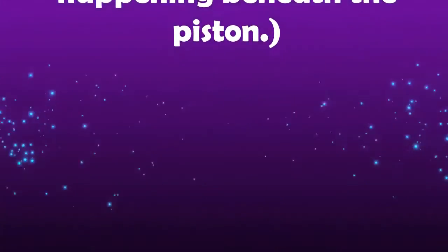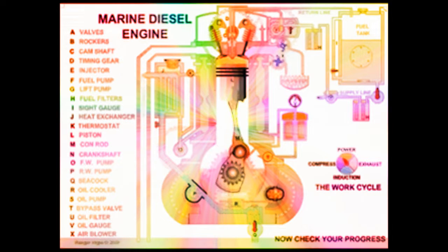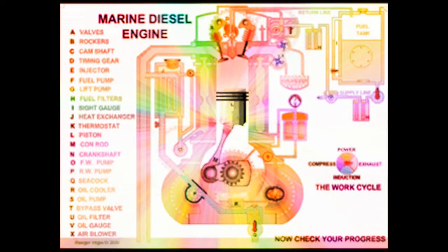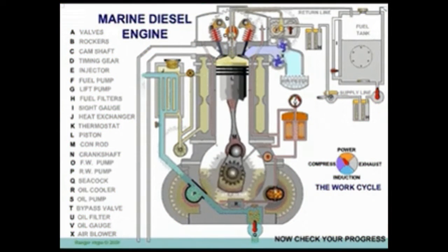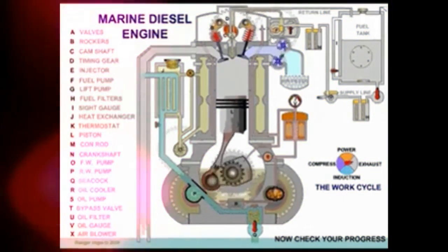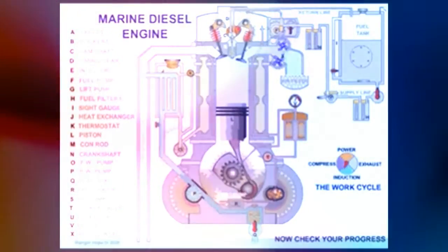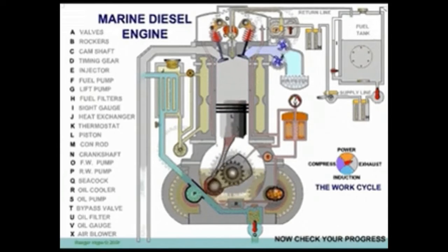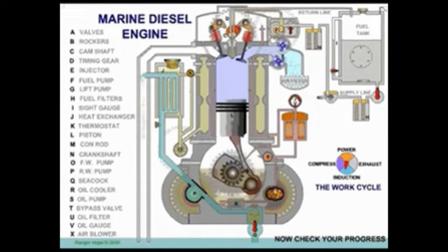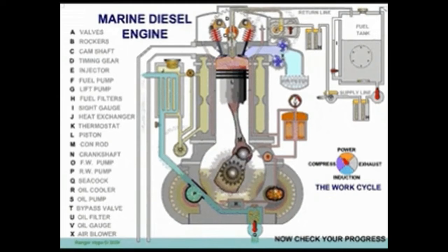At the same time, another intake stroke is happening beneath the piston. Power. At the top of the stroke, the spark plug ignites the fuel mixture. The burning fuel expands, driving the piston downward, to complete the cycle. At the same time, another crankcase compression stroke is happening beneath the piston.